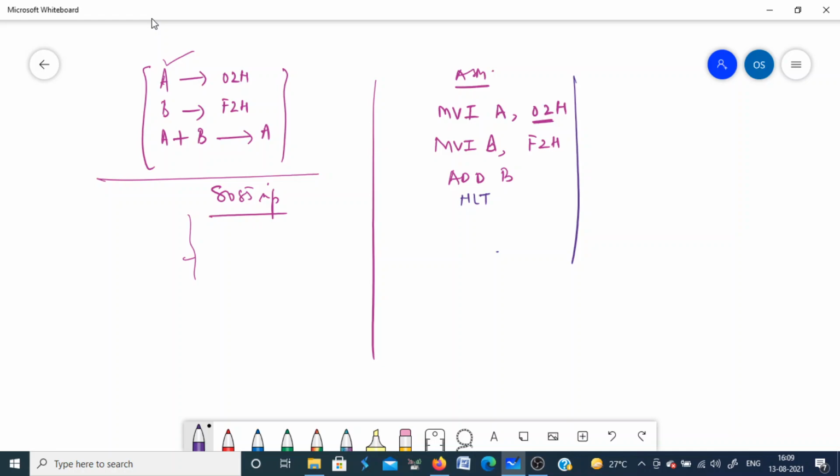Whenever the microprocessor reads or fetches this instruction, it will stop executing the program. So this is my assembly language program. Now if you do a manual assembly or hand assembly, you have to convert this assembly program into hexadecimal codes.